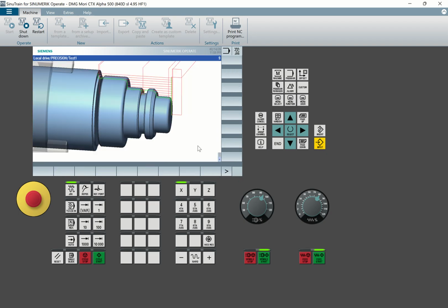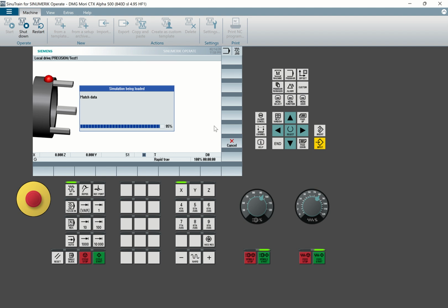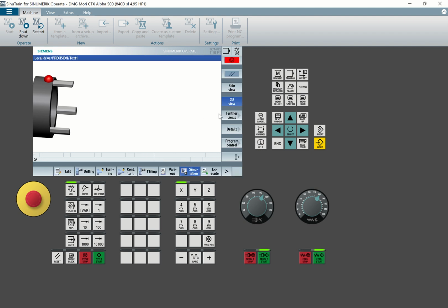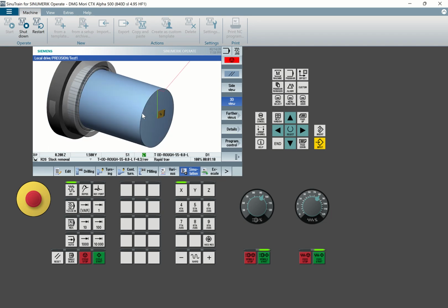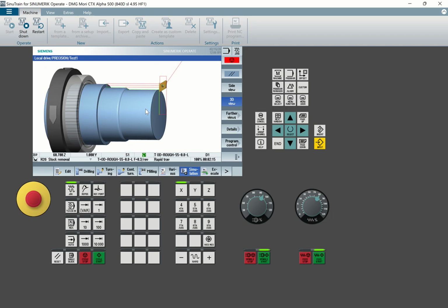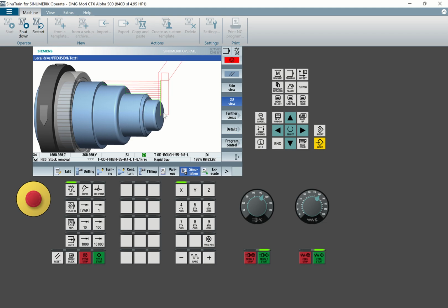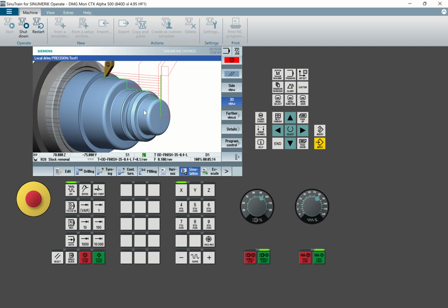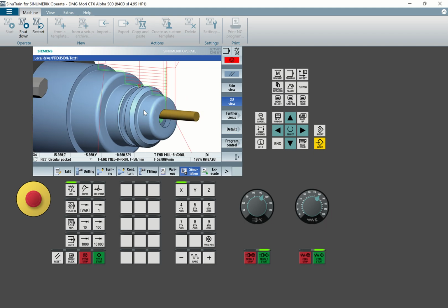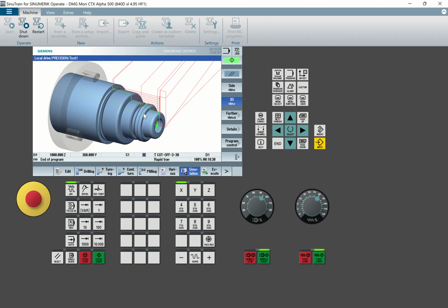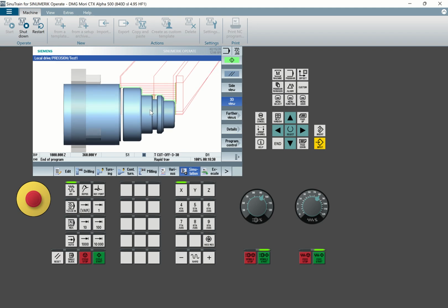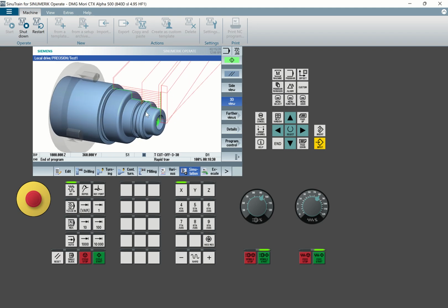Then you can do a simulation. We see how it will be doing now for milling, because this is now a turn mill. We're able to do turning at the same time we do milling before it does cut off. So we can do this part, we call it pocket on the face. You can see what the machine is doing now, pocketing on the face. This is how you can include various operations.